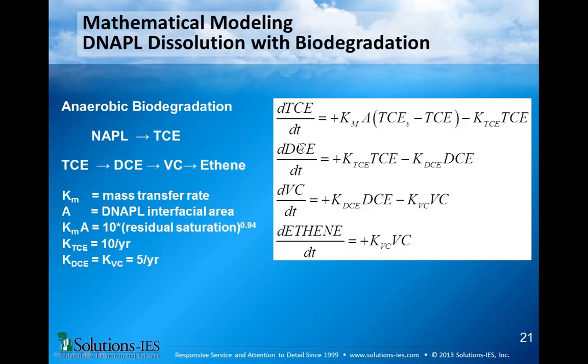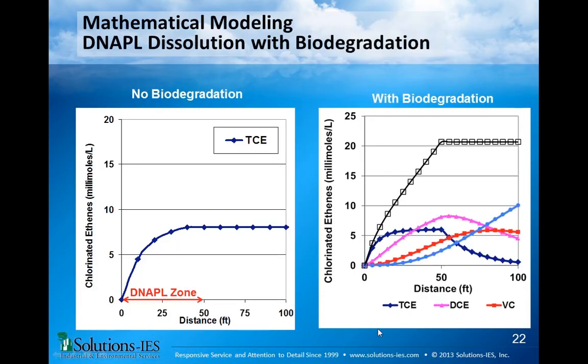I'm sure you've all seen these kinds of graphs before. This is from Ashley Eady, and she showed for degradation of TCE, you got pretty good TCE degradation. The best was at 7, but even at 6 or even at 5.5, degradation was slower, but you still got it. So for the best degradation, we probably want a pH of 7, but 6.5 is probably fine for pretty good degradation.